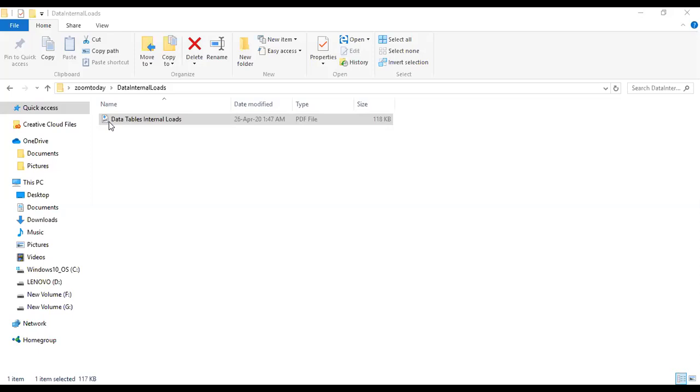So we need both types of heat from the persons, that is latent and sensible both. From these two columns, you can calculate how much will be latent heat. Sensible is 0.75 of this 70. Here, sensible is 0.6 of 100. Here sensible heat load is 0.5 of 150. So these are total heat. This column shows total heat. This column shows the percentage of sensible heat of the total. So you know the sensible heat, you know now the latent heat.